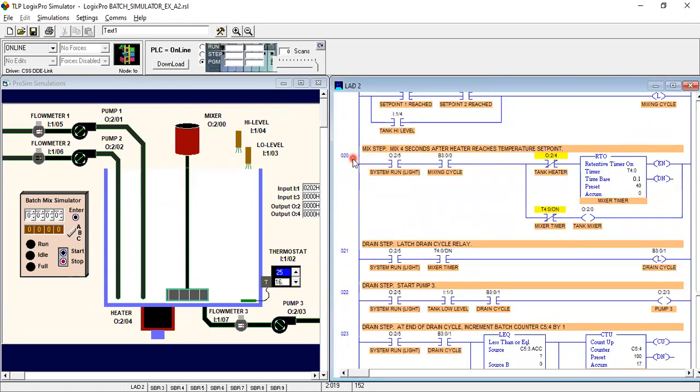And in the 20th rung we have to discuss controlling the mixing setup. When our two different types of liquids are mixed, we use these rungs for controlling the mixing. So this is the NO instruction, and we have to put in the output address for controlling.